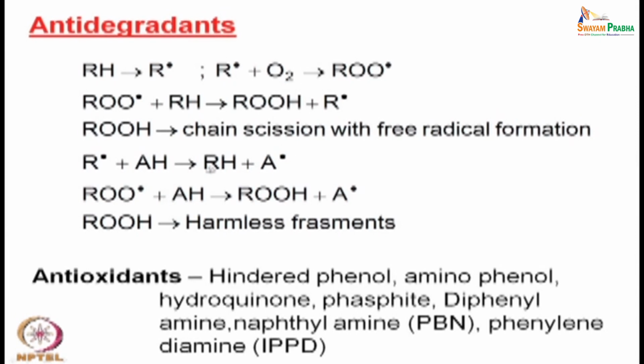What happens in the other cases? There are R dot and RO dot peroxy radicals, which are also taken care of by this anti-degradant, forming hydroperoxide and A dot, and again the hydroperoxide will also be converted to other harmless fragments.